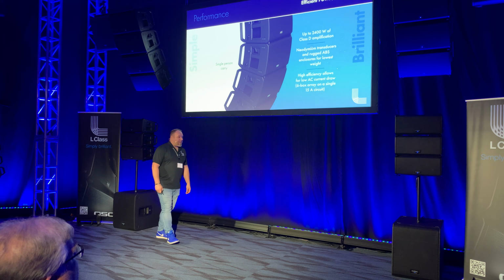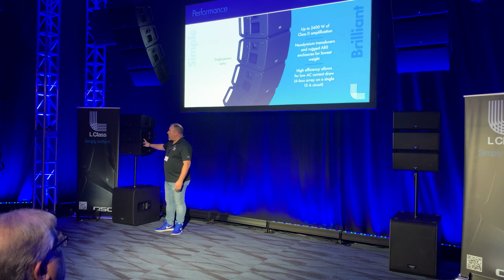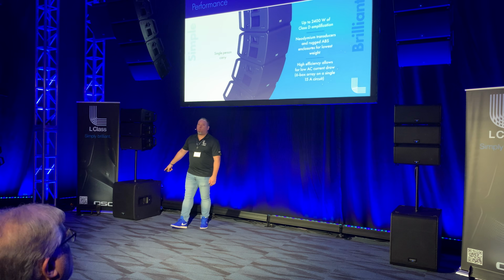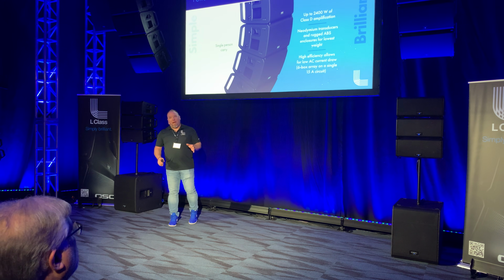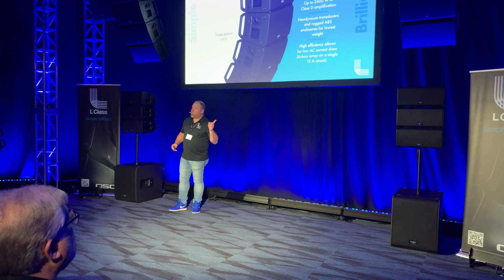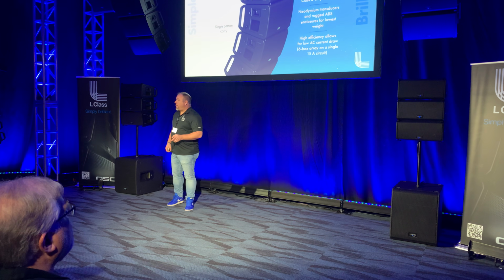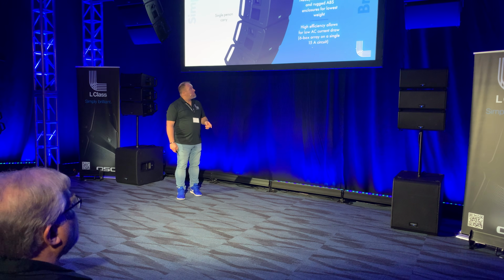As far as efficiency and power, you've got about 1,300 watts of power running the LA108, 2,400 watts of power in the LA112, 3,600 watts of power in the LS118 subwoofer. We're using all highly efficient Class D amplifiers. As you can see above me, you can actually have up to 6 boxes on a 15 amp circuit at full power with plenty of headroom for output. So that's less power drops and less generators at the gig.